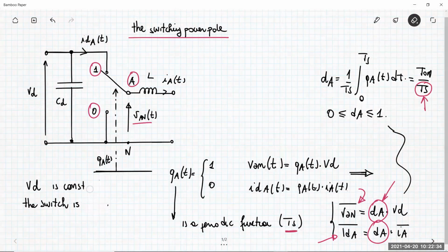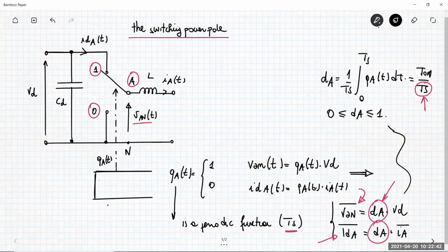So it is for this reason that all the blocks that generate the unitary switching function are called modulators. Okay, so we have here a modulator. And in this specific case, the modulator acts on the width of the pulse. So this is a pulse width modulator, PWM for short. This pulse modulator generates this unitary switching function on the basis of a control voltage.